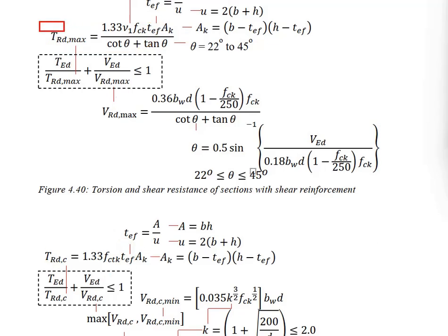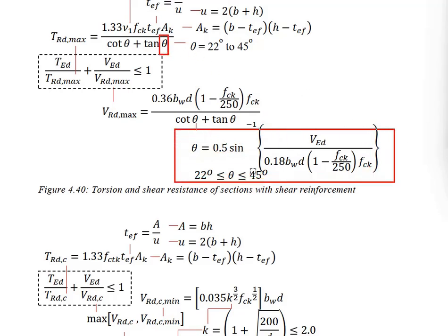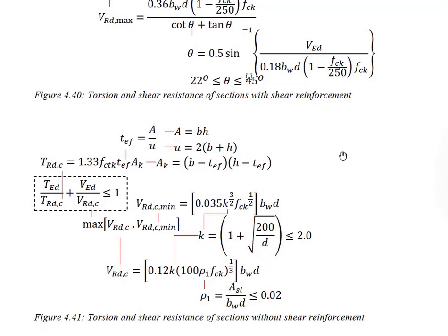First, to work out the TRd,max, you need a strut angle, and this angle is obtained from the shear angle. Second, if you are talking about those without shear reinforcement, it has no concern with fck. Instead, it is more relevant to fctk. And since it is not developed on the imaginary truss model, no strut angle is required in the formula.